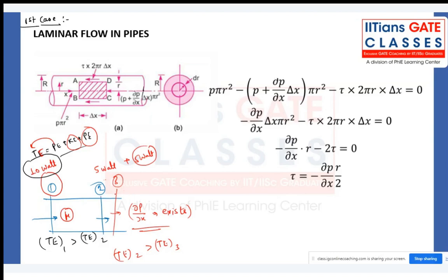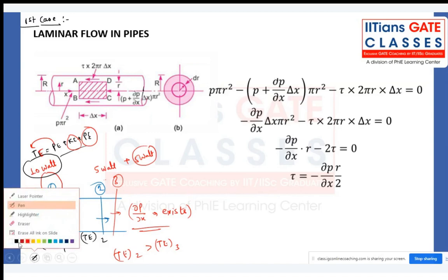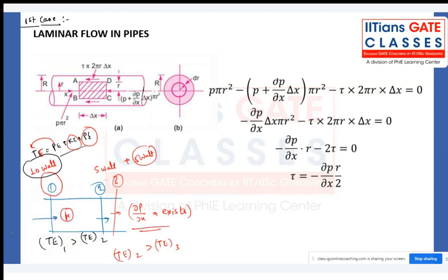And that's a very ideal situation, when we have the pressure energy also constant. That means there is no head loss due to friction. There is no power gone. Whatever power you're supplying, exactly you are able to flow. You can imagine some fluid flowing in a nanotube pipe, a carbon pipe, where you have a fully smooth surface finish, right? In fact, even there it is not possible to achieve that condition in reality, but still I'm saying to imagine where the total energy remains constant at all the points in a fully developed flow, remember, in a fully developed flow.